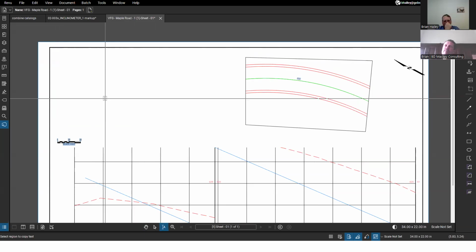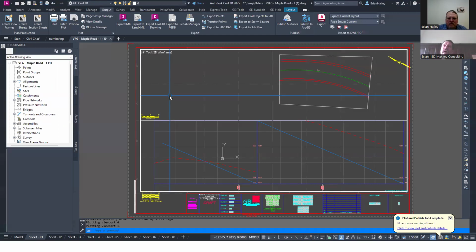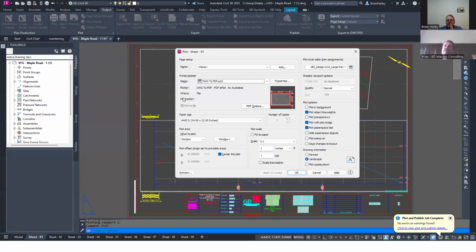Sorry, Chris said in the comments, it happens when you're printing from Bluebeam, not Adobe. Since Bluebeam ties into the CAD stuff, it does things like that often because it's trying to maintain a lot of the intelligence, understanding this is a line, a curve, whatever. So oftentimes you can also go into Bluebeam and try to flatten that PDF and then see if that print works. Because basically you're saying remove all of the intelligence and just give me images to print, and it will do it a little bit better.